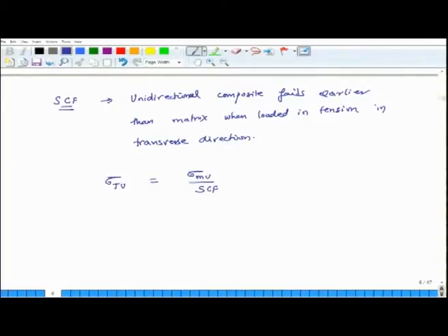Now, in this course we will not learn how to compute this stress concentration factor. You can find this stress concentration factor by developing models of your system using FEA methods, or there are some already some approximate solutions which are published in existing literature, and I will share with you one estimate of such a stress concentration factor.